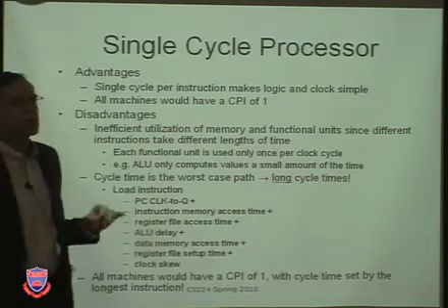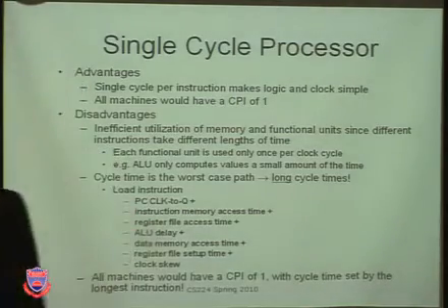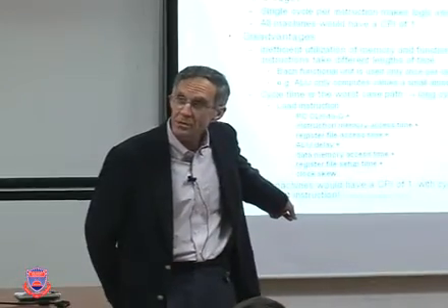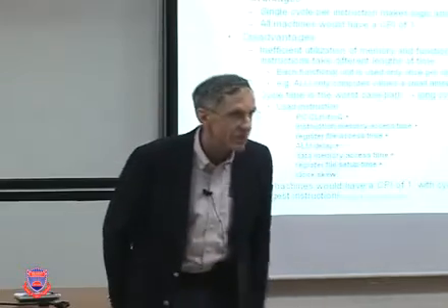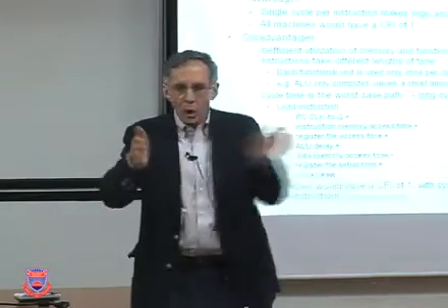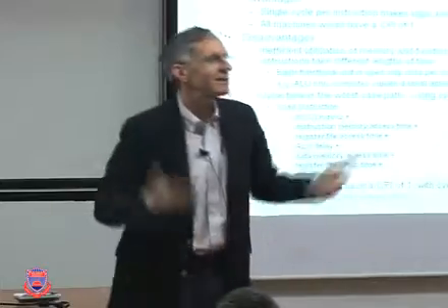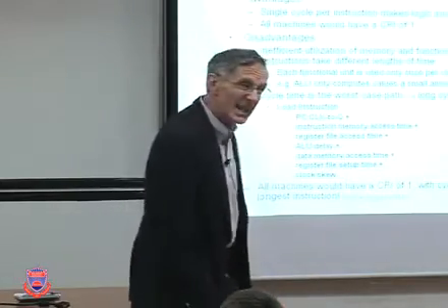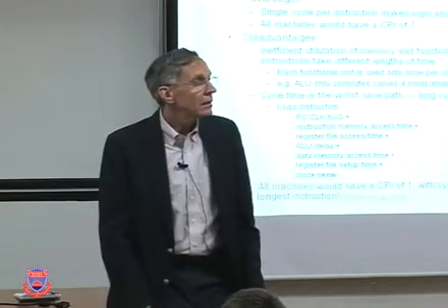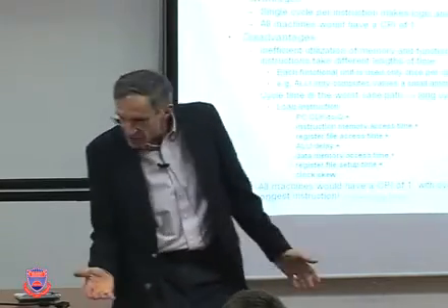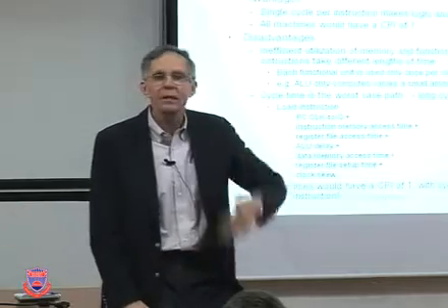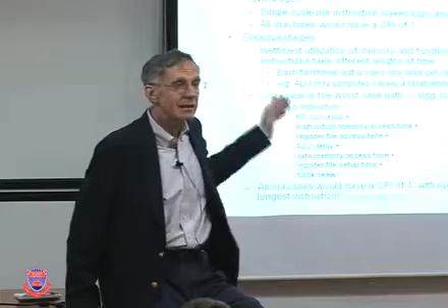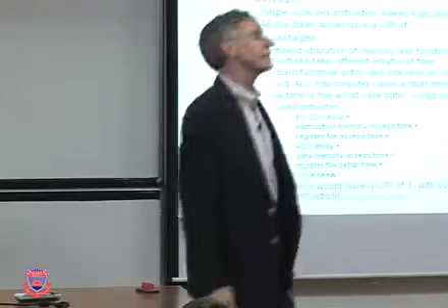Now, if you have a single cycle processor, what does that mean? Every instruction executes in one cycle. That means the clock cycle which we determined for the slowest instruction will be the clock cycle for every instruction. We can't have a variable clock cycle that says, go short for this one, go long for this one, short for that one. You can't have a clock cycle that varies. The clock is, as you know, on a regular timing pulse, and so therefore the edges of the clock will have a fixed separation in time. It's not going to be variable. The clock rate is like a heart rate. It's a regular rhythm. So therefore, in order to do this instruction, it has to be that slow. Therefore, that's going to be the clock cycle time for all instructions.